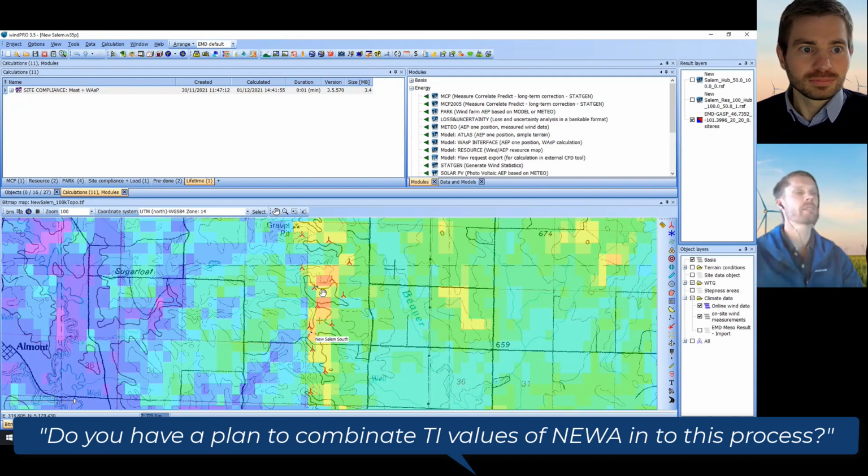They might actually match on average, but for loads, we need the 90% quantile as a function of direction and wind speed. And in general, there are big problems there for mesoscale data. They can't predict the standard deviation, and they generally tend to underestimate it significantly at higher wind speeds, which will significantly underestimate the load.